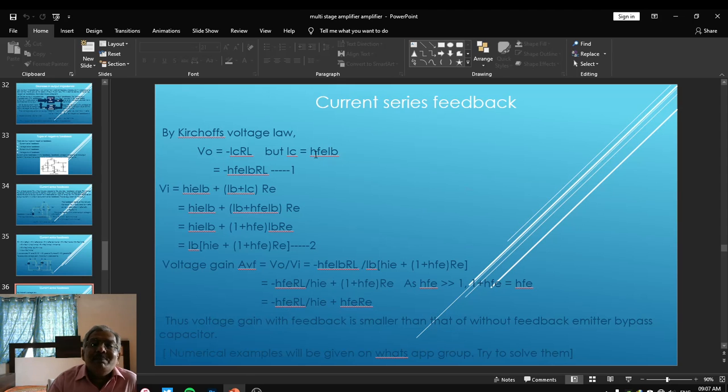HFE is nothing but beta. Put this value in this particular equation so as to get VO is equal to minus HFE IB RL. Let me call this as equation number 1. Now this is the output voltage which we have calculated.